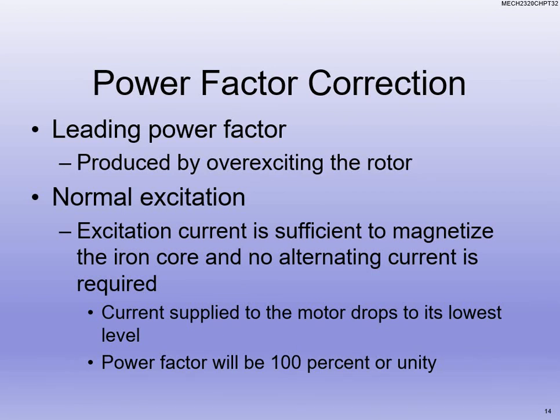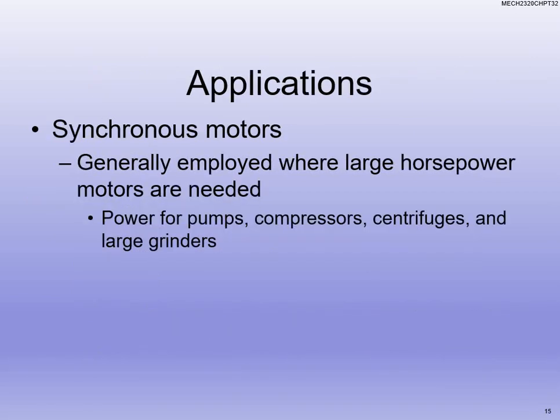And we'll step into that in some other lectures and some other labs, but just understand that that's really what we're doing. We want to make sure that our power factor is roughly around 100% or unity when we do that. Okay, and where do we use this type of motor? Where are we going to use a synchronous motor generally? All right, we're talking large horsepower motors for pumps, compressors, centrifuges, and large grinders and things like that. Big horsepower motors, very common in industry as well.